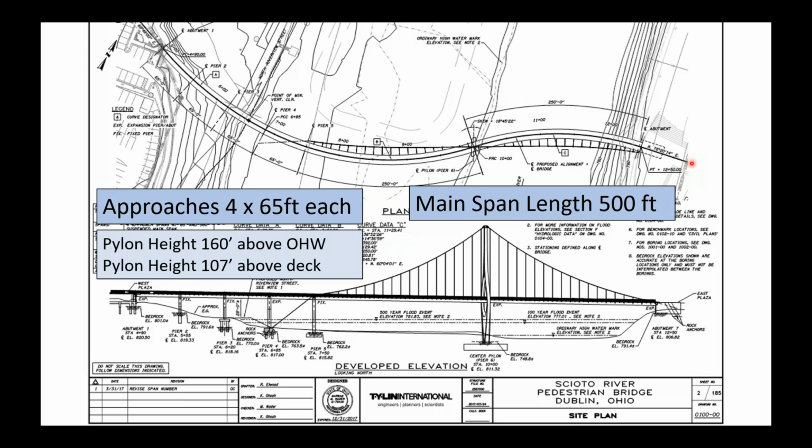straight bridge. But in addition, with that single plane of stays connected, you saw the advantage of the ability to carry the torsional or the horizontal component of the anchor load in an arching effect in plan, and that is an advantage. It can be done without that, but really it does benefit the bridge from having that curve. But in short, it was primarily selected aesthetically.